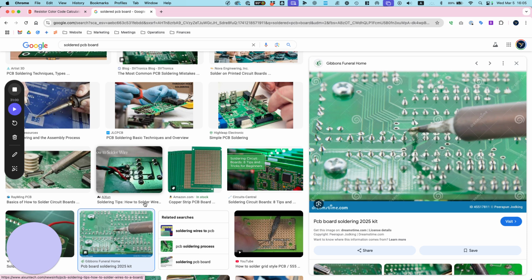Okay, so let's hook it up. I'm going to turn down this voltage before we plug it in. Okay, I'm going to turn up the voltage. And there we go. I actually don't even need to turn it up that high. I'm just going to turn it up to 3 volts. Okay, so what do we remember from parallel circuits? What's the voltage across each device? Huh? 2.2 volts.